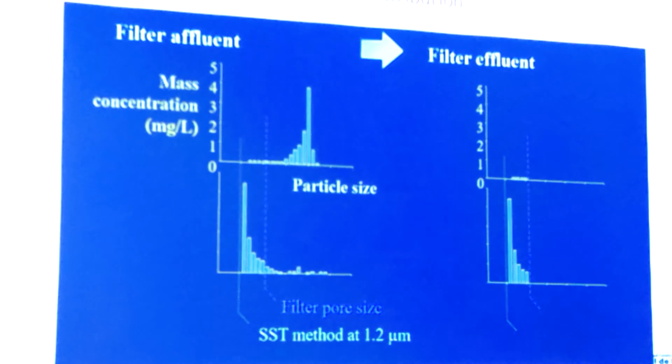Remove the solids. One thing that we maybe need to figure out is what the sizes of those solids are. If you want to use a screen drum filter, I might wonder, how do you know which screen size you should use? A 90 micron, 60 micron, 40 micron? How did you choose the number? A long time ago, I had that question when I was doing my PhD, like 25 years ago, more or less.